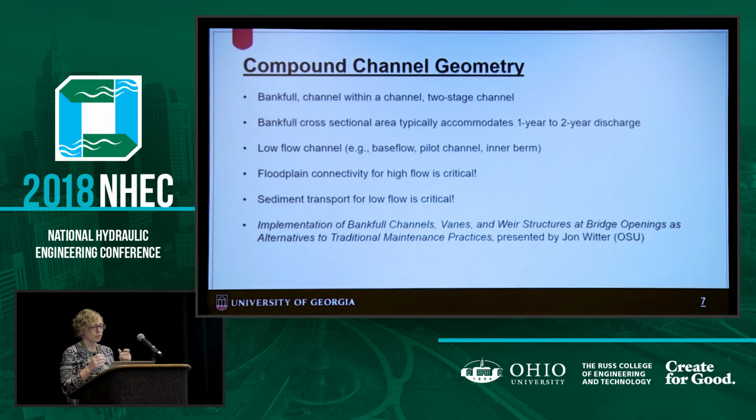So when you have compound channel, you've got two things. You've got floodplain connectivity, and this is critical especially for the high flows. So you want to put the water up on the floodplain. It brings down the stream power inside your channel, so it reduces your velocity and your shear stress. For low flows, it's critical that you account for sediment transport for the more frequent events, so that now we're in the 1 and 2 year or even more frequent events. So that's critical. So bankfull is a tool for you, and actually John Witter is going to talk about that a little bit too, I believe.